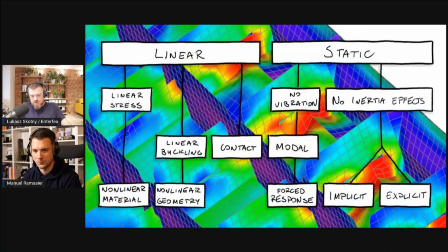And it doesn't have to be a perfect match, let's say 10% from one side, from another side, you want to be clear. It's bad enough. And then if you manage to land something like this, you're kind of okay. This rarely happens though, because normally structures have a lot of modal frequencies. You just have the first one, and if you happen to have a load that is lower than the first one, you're happy, right? But if the load frequency is higher than the first one, there might be a 76th modal pattern that will perfectly hit your load.